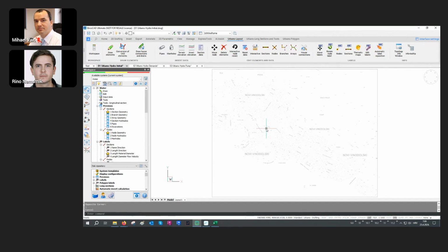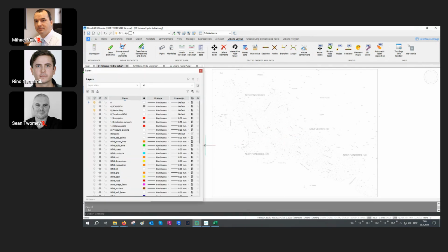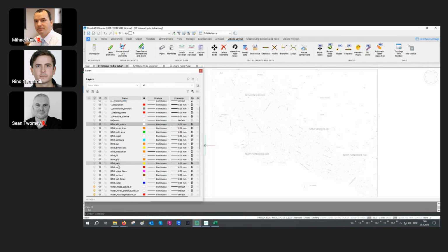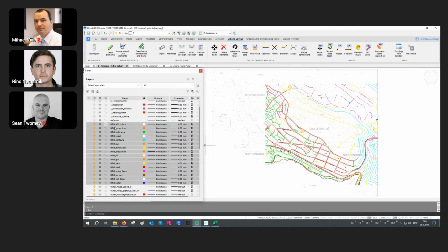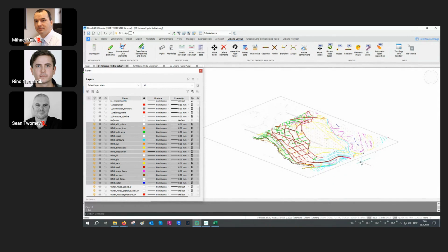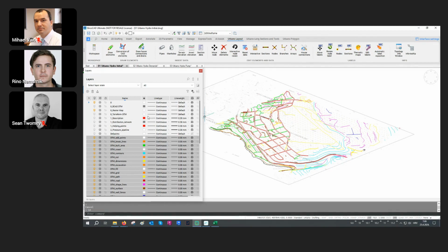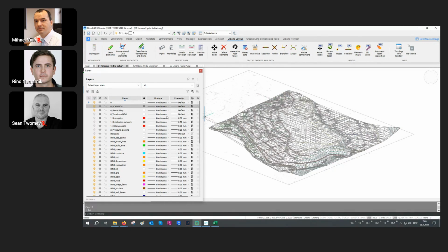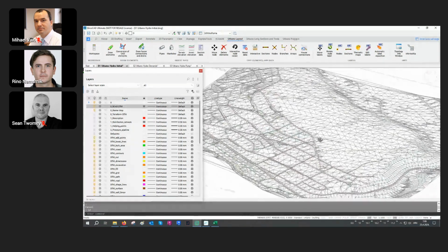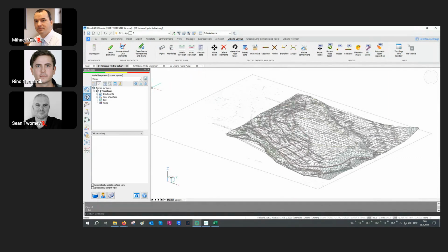As you can see here in this drawing, I have only this raster image of this area, but also if I open BricsCAD Layer Manager, here I have some additional layers, these DTM layers that I will now turn on, containing these source elements that I use to create two DTM surfaces. So these are just 3D points and lines with elevations. Using those source elements, I created one BricsCAD DTM, which we can see here, these triangles, and also using the same source elements, I created a Softplan Terraform DTM. So this is our own DTM modeler.